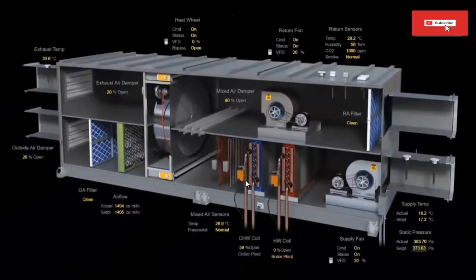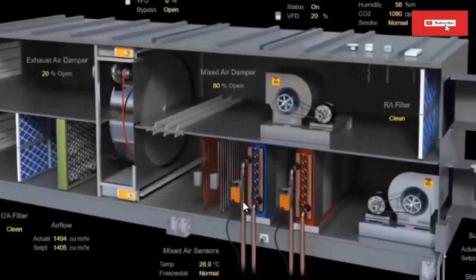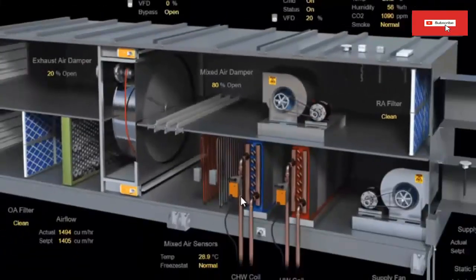As for the recommended ppm values, they should usually be between 400 and 800. In this case, air renewal must be increased and recirculation decreased, which in this case is 80%.